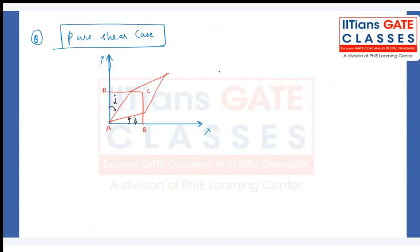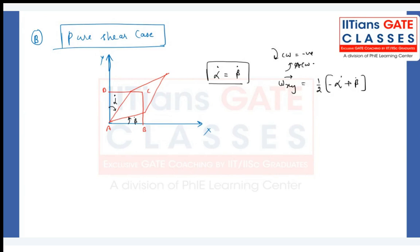Here what is happening is alpha dot is equal to beta dot. Don't write minus beta dot, plus beta dot. Both are rotating equally, but in the opposite sense. Then tell me, what is the omega xy? By the definition, we know that it's the average of that. But beta dot will be positive and alpha dot will be negative according to our sign conventions, because alpha dot is clockwise, and clockwise we have taken negative, anti-clockwise we have taken positive.